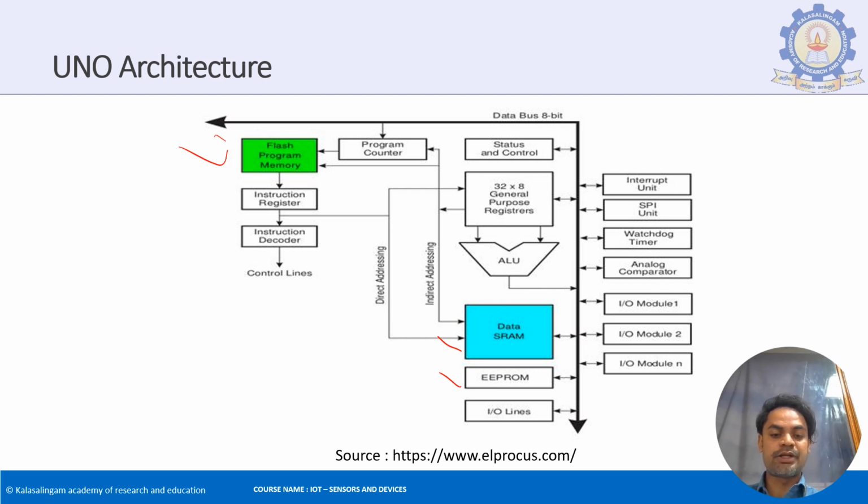This is for storing the data over here. So from the instruction, you will put it into a register, which is going to be decoded. When this register is having the instruction, the next step is to decode that instruction, to understand what that instruction is going to do. If it is A plus B, it is understood that I need to add two data. So the machine needs to understand it by decoding it, and accordingly the control lines are given stating that, okay, get the value of A from here, get the value of B from here. So the control lines are coming over here.